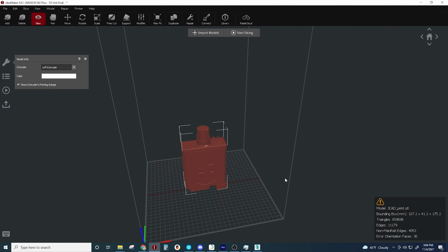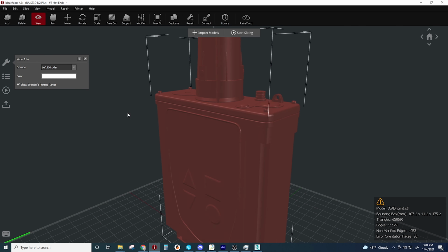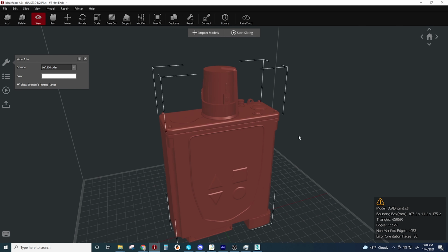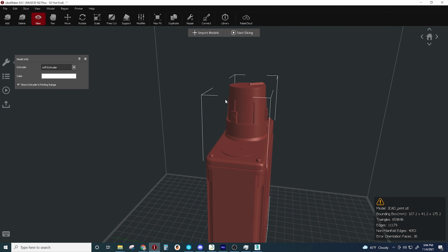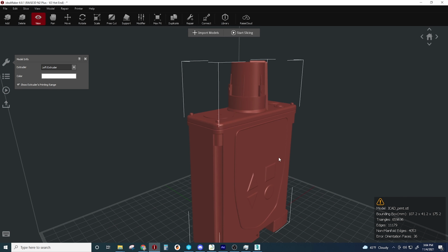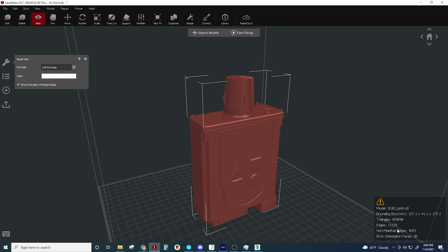Okay, so just another quick note. I am getting some errors, some non-manifold edges, and some issues with orientation faces. You can run a repair to try to fix this. Basically, there must have just been a couple of things that I missed. But I went through all the important stuff. Everything has back faces. There just might be some unwelded vertices in certain areas after the Boolean. So that's probably what this all means.